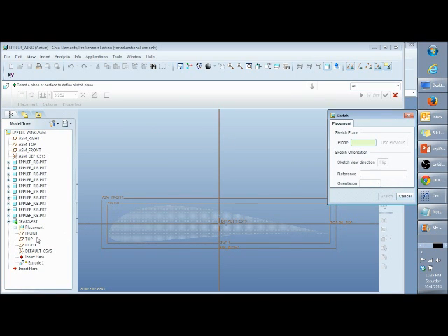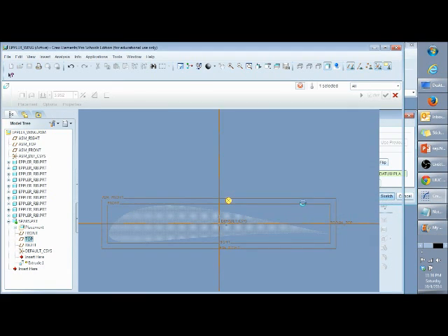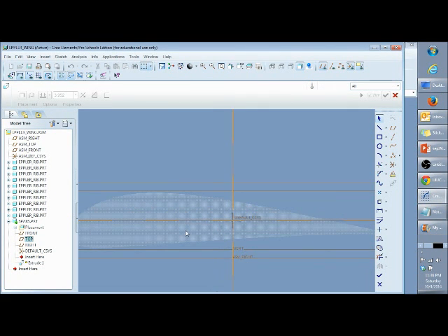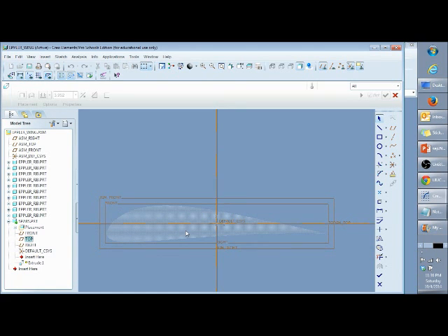Very important to choose the plane not of the assembly, but of the plane in the actual part. This is just to make sure that your files are all nice and kept clean, and it will create, I believe it's called a circular reference, and it shouldn't really be that big of an issue with files that only you are using.